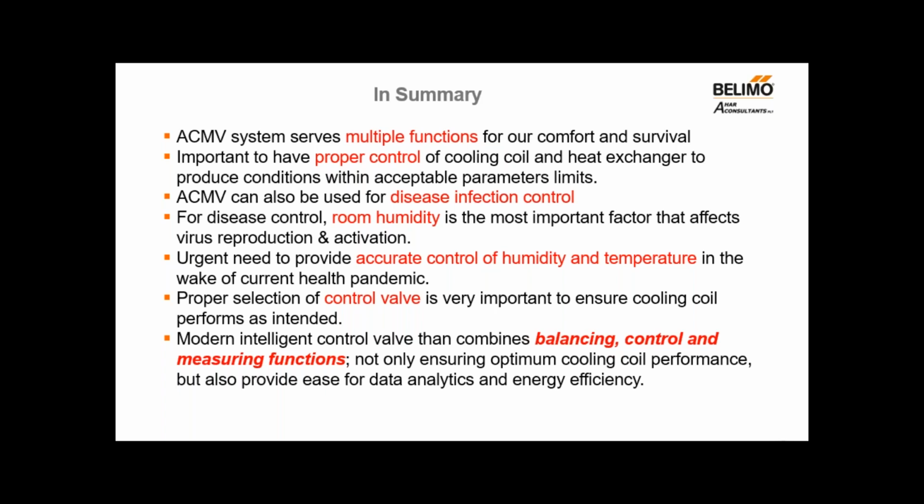Proper selection of control valve is very important to ensure that your cooling coil perform as intended. Modern intelligent control valve that combines three functions: balancing, control, and measuring functions, not only ensure optimum coil performance, it also provides ease for data analytics and energy efficiency.